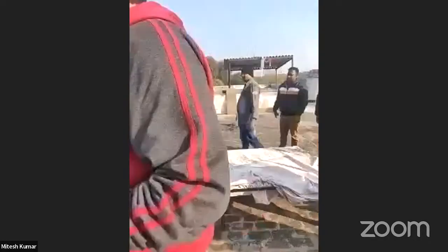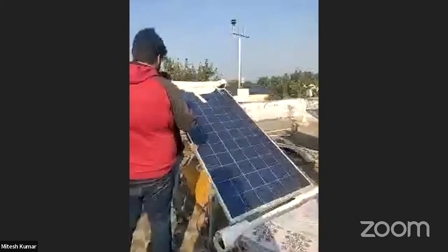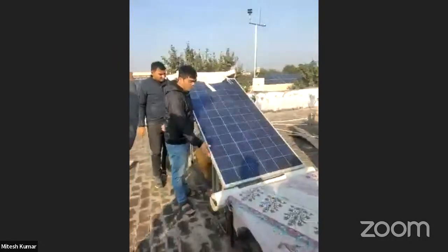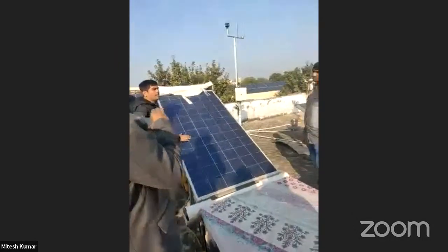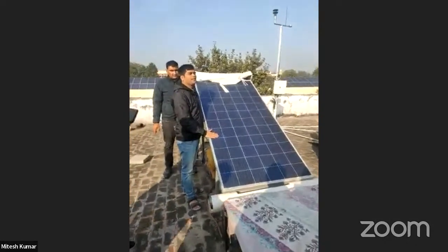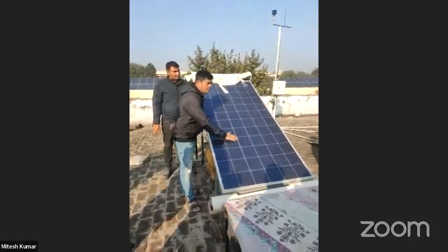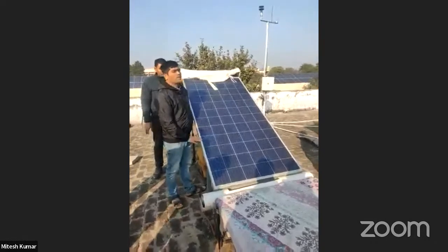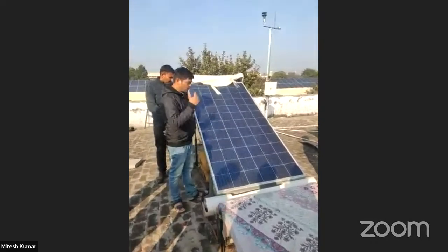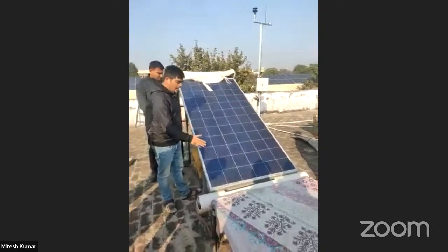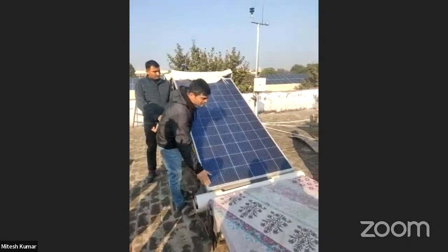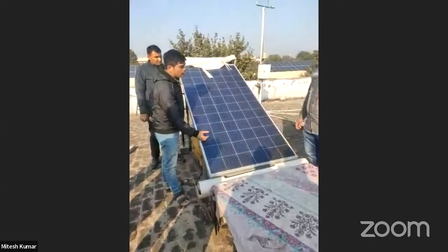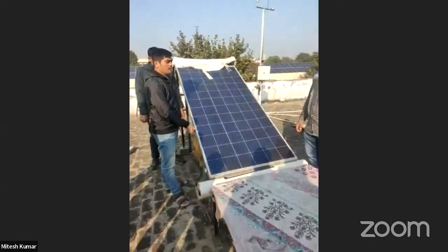These are the PV collectors. By photovoltaic effect, the solar radiation is converted to electrical energy. When the radiation is falling, this plate converts the radiation energy into electrical energy. These are called the fingers, for collecting the current in a particular manner. We can arrange them in series or parallel for raising the current level or voltage level. All these fingers are collected at one side by a common wire, and this common wire is also put to the outside for collecting the voltage and current to the load.